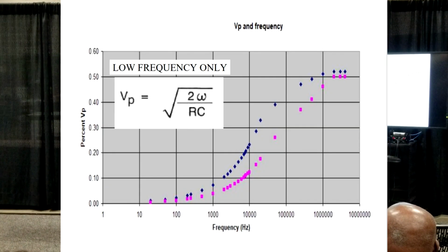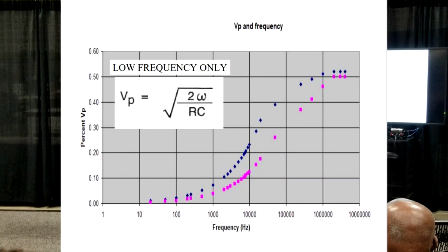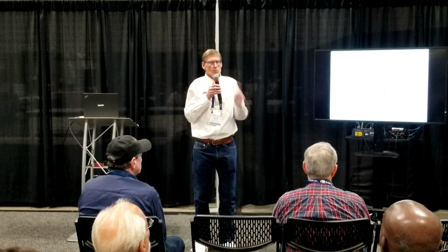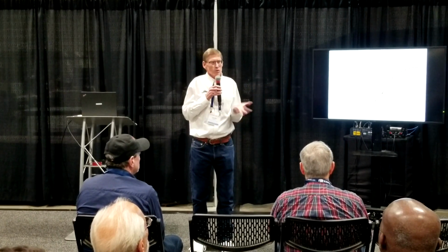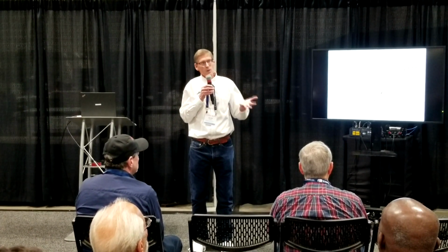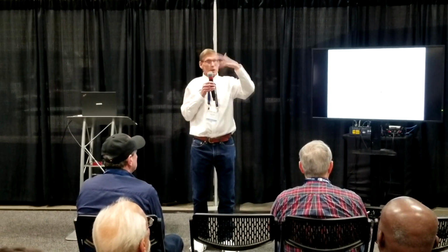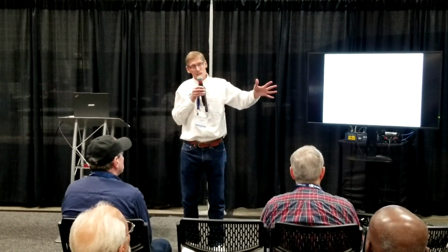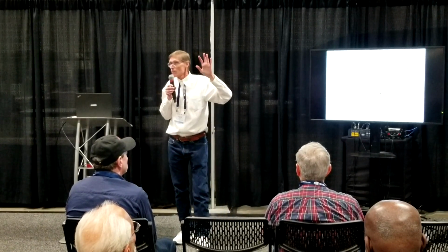And it is a composite dielectric. Even though the conductors in this case are insulated with FEP, someone here will say, well, it's 1 over the square root of E, and I know E of Teflon is 2.1 because I'm really knowledgeable, and that's 69%, but you're way below 69%. That's because there are other parameters in the cable that Mother Nature averages out. She says, okay, you got some FEP, but you also have some other stuff going on, so all I'm going to give you is 50% of the velocity because I'm going to give you a composite structure dielectric propagation.